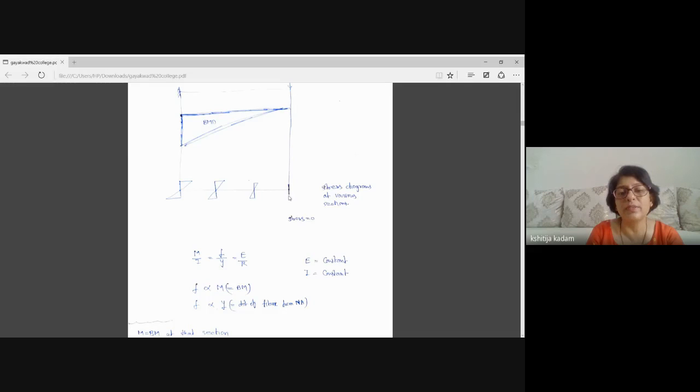So the value of bending stress across the thickness is 0. Whereas if you see this another location, at this location there is some bending moment. So the bending stress diagram is an inclined triangular shape with small values at the topmost and bottommost fibers.